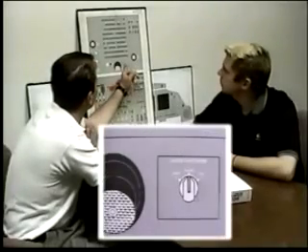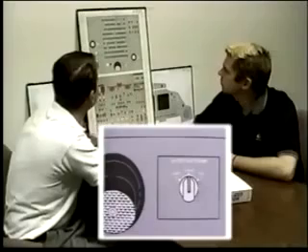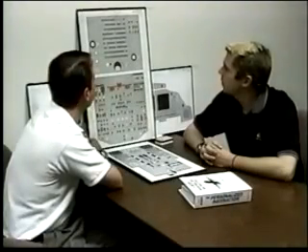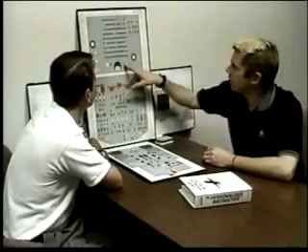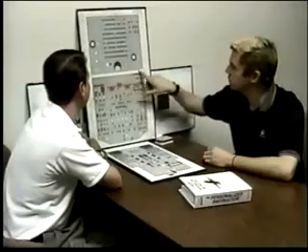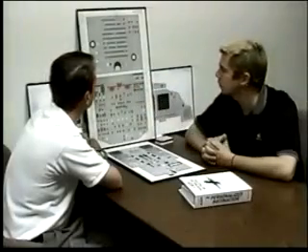Audio switching. There's a selection for Captain on 3 and FO on 3. When would you use this? With the Captain on 3, I would use that when the Captain's ACP has failed and he wants to use the number 3 ACP, audio control panel.